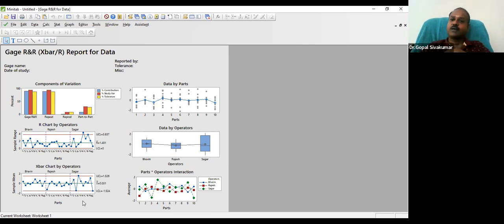Now I am plotting them in a control chart. What will happen? The proportion of the samples I selected close to the target will definitely stay inside the control limit. Am I correct? Yes. But the proportion of the samples close to the spec, where anytime a customer might reject, according to me those are bad. Definitely those points will be beyond my control limit, and those points should appear outside the control limit. Look at the X bar chart. Almost everything is inside the control limit.